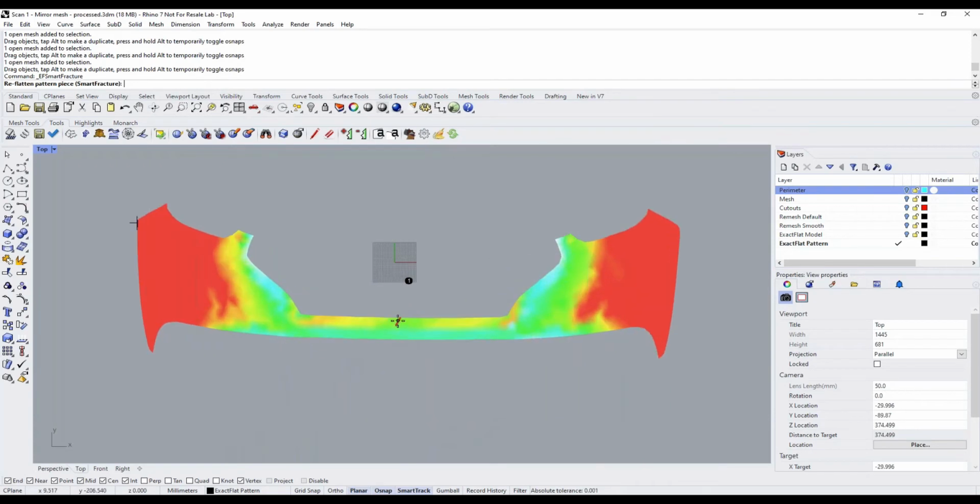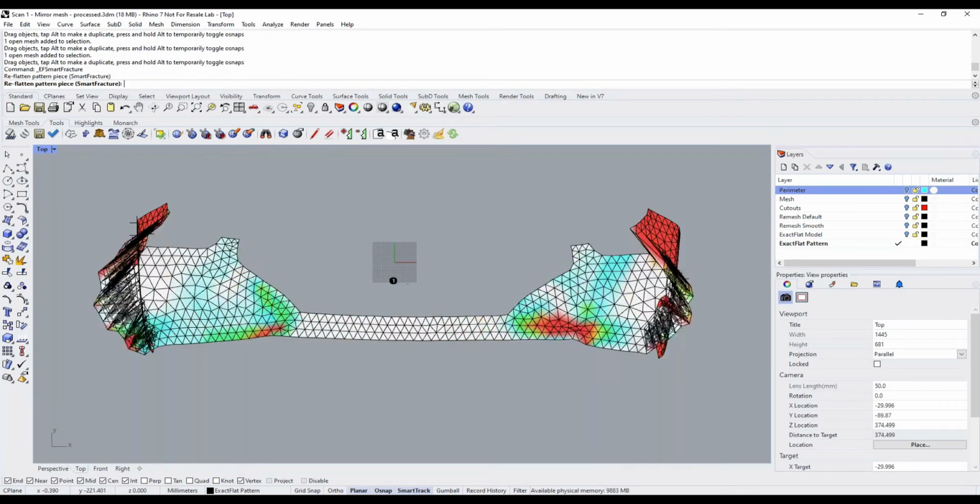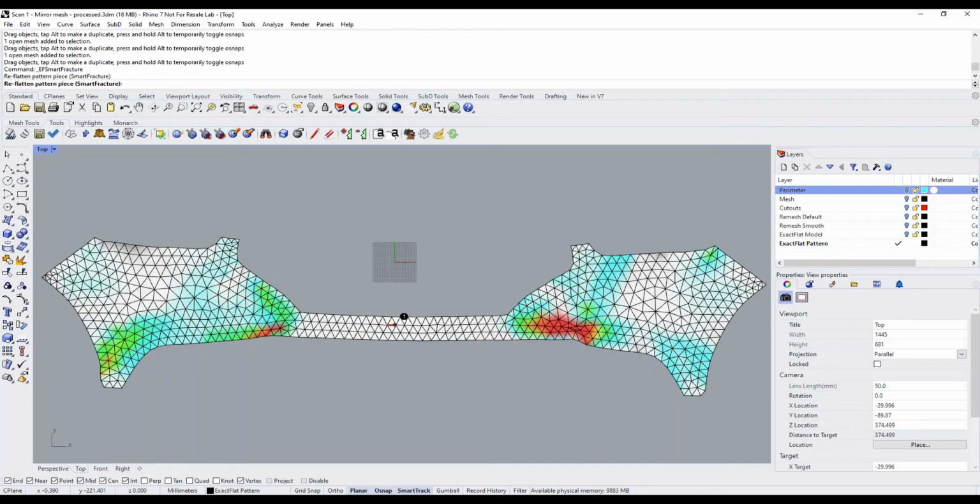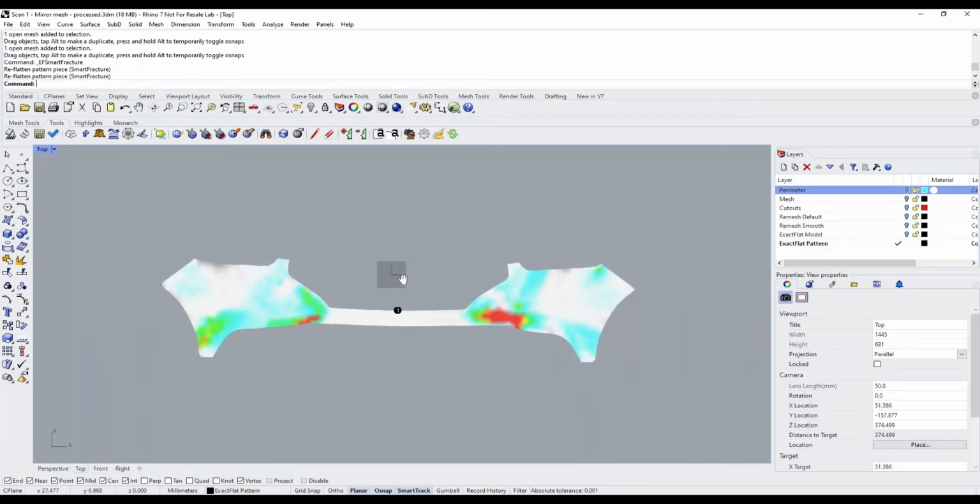And second, I want to press as much of the strain out towards the edges of the pattern before I start the optimization process. So I'm going to pick a spot right here in the middle, and we can see the tool pressing all that strain outwards. We no longer have our fold or wrinkle in the corner here, and we can see from the color that we've greatly reduced the strain on the part down to much more reasonable levels. We have mostly white everywhere with a bit of cyan, and in a small localized area we have some red here. So this is an ideal starting point.